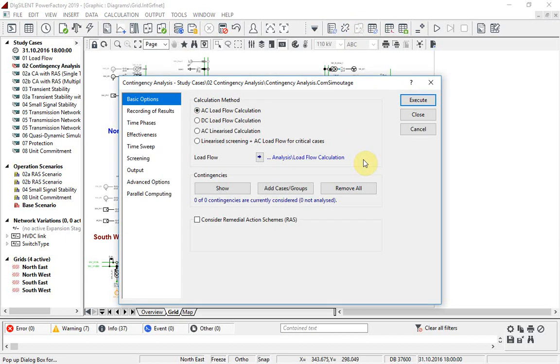There are three main calculation methods. The first is a calculation using a full AC load flow. The second is a fast DC calculation, which calculates active power but uses nominal voltages. The third is an AC analysis method that represents the contingency case by using equivalent injections to reduce the flow through the faulted area to zero. This speeds up the calculation, so can be useful for large numbers of contingencies, but it is a more approximate